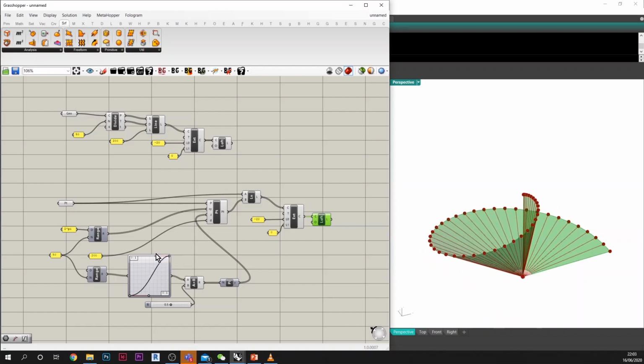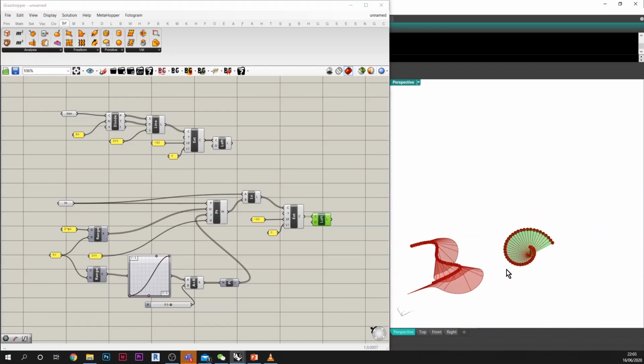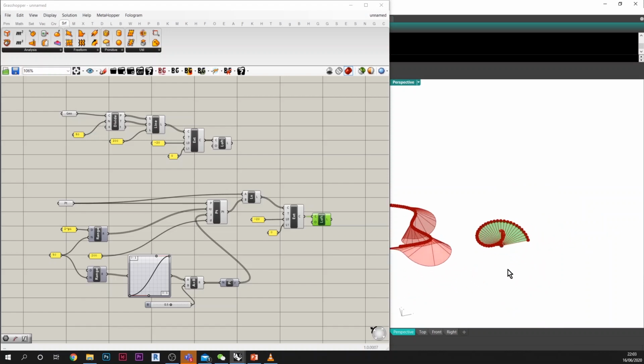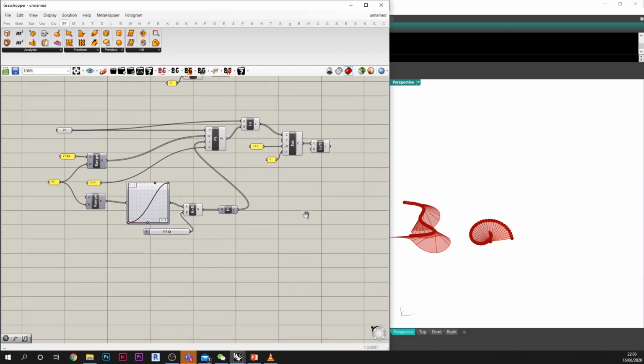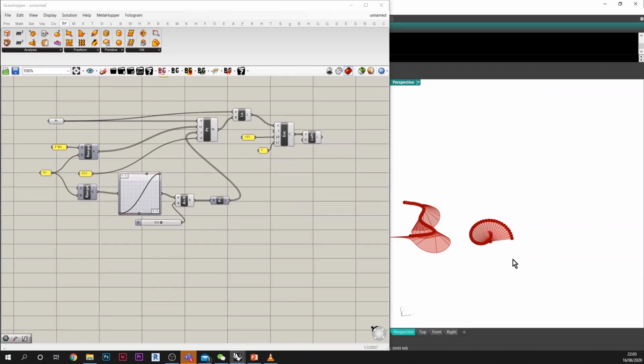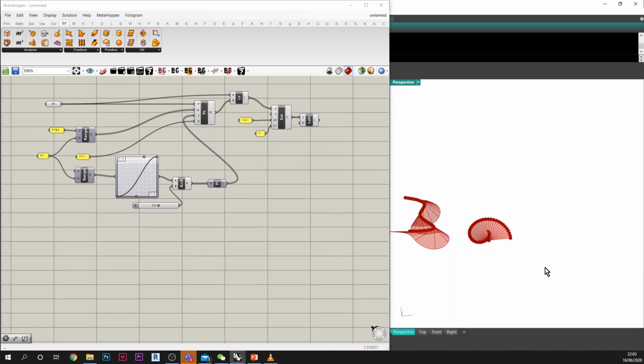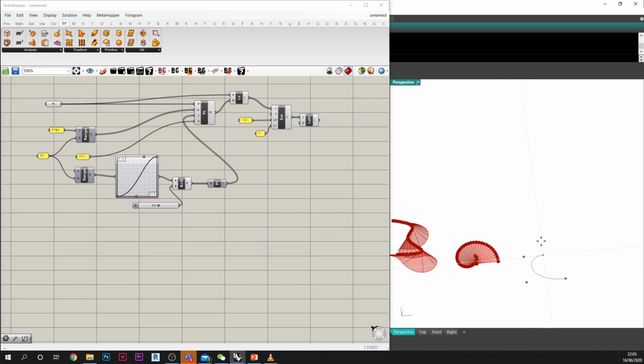Okay. For the last one, the cylindrical surface, let's do something which is more likely to be a design of something, and we will try to do a volume, in fact, out of two cylindrical surfaces. For that, we'll first do a curve in Rhino and check that this curve is possible to be mirrored along the XY axis.